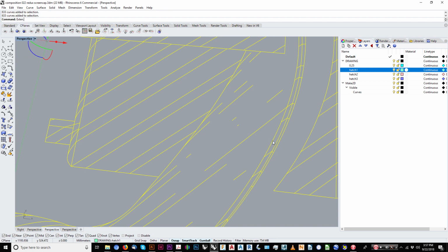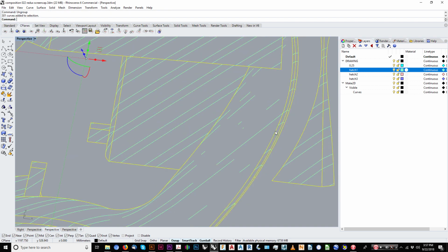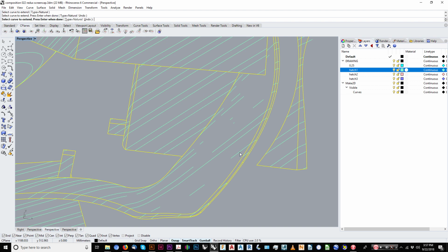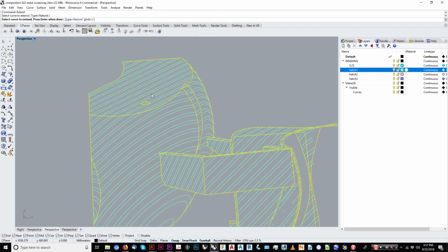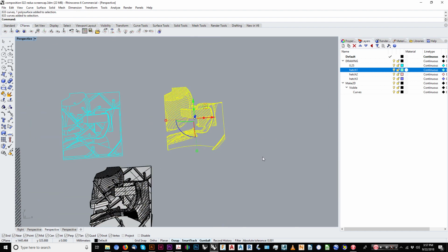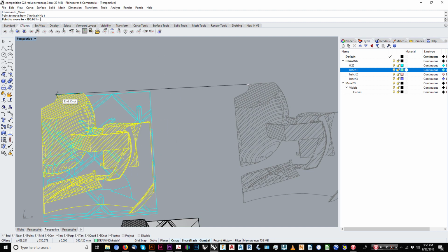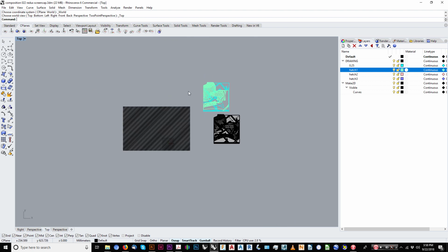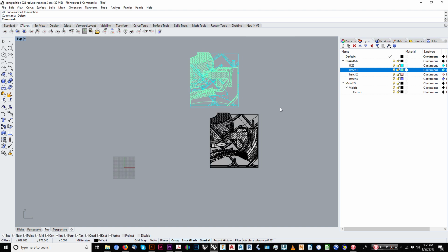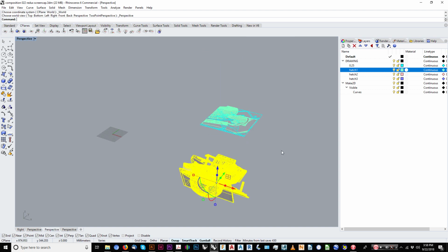So now we can see there's some issues. We can use the Extend command. Let's actually not be so lazy and let's extend it as so. And obviously for the sake of this tutorial we will just leave that there, but this one is really bothering me, so let's do that. Let's ungroup everything and then group it so that all the underlying groups that Make2D made aren't a factor. So now we're at this stage.